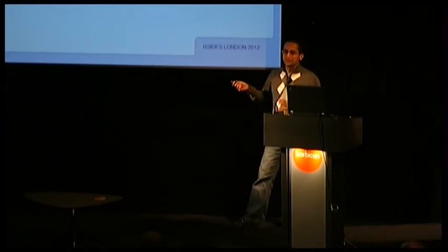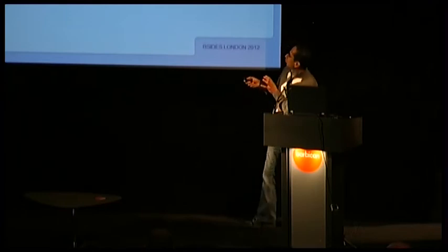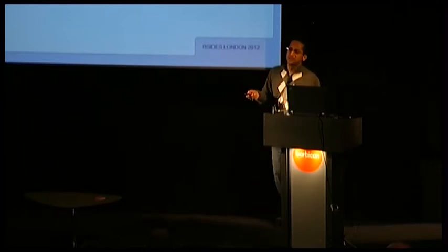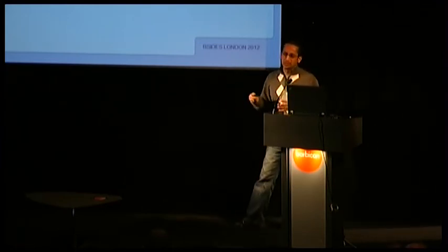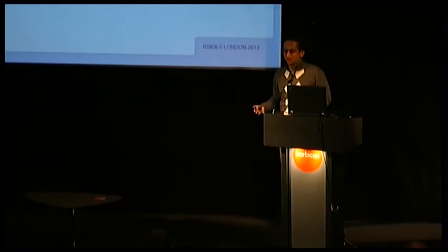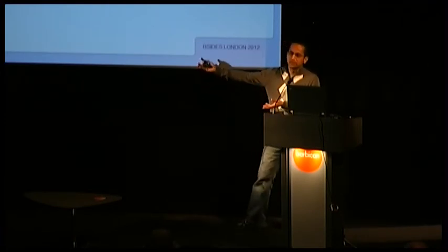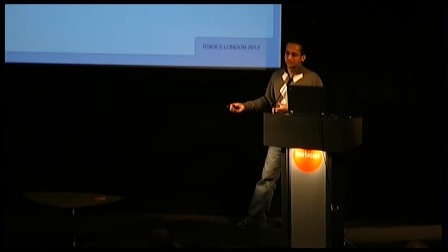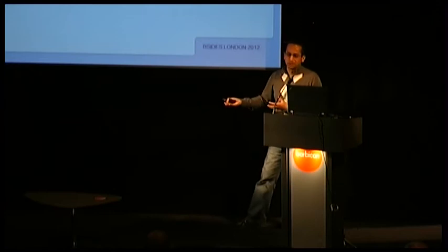Protocol ID is again 2 bytes. It's constant. It's 0 for Modbus. We don't have to worry about it. And length is basically the length of the packet. The last 1 byte, which is unit ID, is quite interesting. It basically tells the server which unit I'm referring to. So when I ask for a temperature or pressure or some sort of a reading, I tell that this reading is for the sensor number 200, which is connected to you, or the sensor number 500, which is connected to you. So it tells the server which unit I'm talking about.